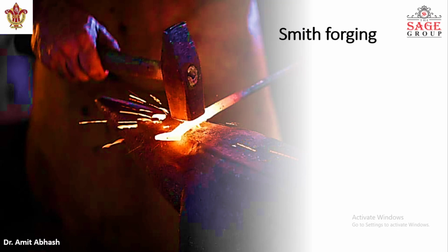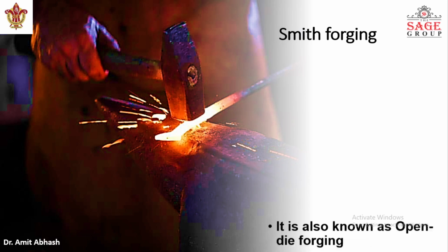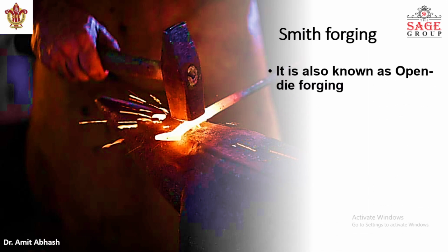What are the Smith forging operations? Smith forging operation is mainly something we will see point by point. At first, it is also known as open die forging. As you can see, the anvil is here, mostly a flat type of anvil we will use, and then hammering will be performed by a blacksmith. Since the whole process is conducted in the open atmosphere, it is also known as open die forging process.